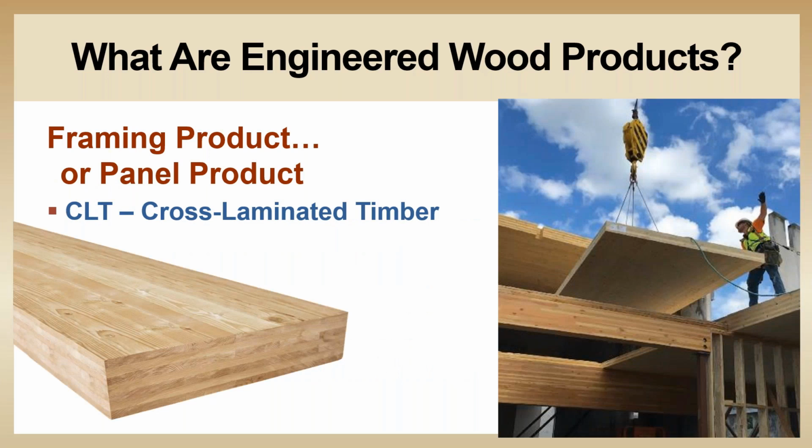Now, cross-laminated timber, or CLT, it can actually be considered in both the framing and panel categories. Cross-laminated timber is made from sawn lumber pieces, which are stacked on top of each other. Now, unlike glulam beams, the orientation of the wood grain changes throughout the depth. And, just like plywood or OSB, CLT panels do have a strong axis span direction. You're typically going to see CLT used for roofs, floors, and walls. CLT is currently code approved for gravity framing.